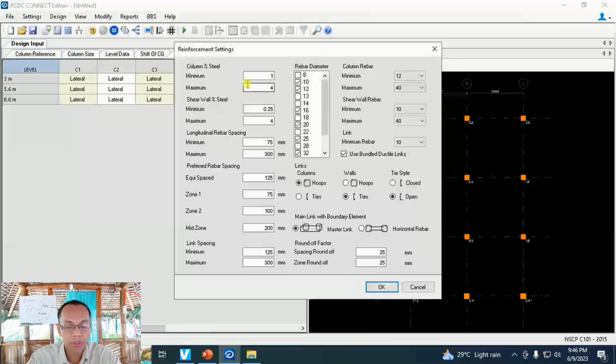In this portion is the steel reinforcement percentage against concrete. Normally, the maximum is 8%. But to avoid over-reinforcement in the region where splicing occurs, and to avoid heavy congestion in such areas as well as in the column beam joint, we reduce 8% down to 4% according to the code. So this is okay here in this portion.